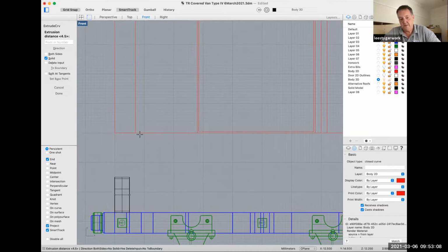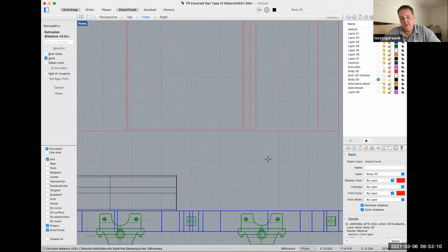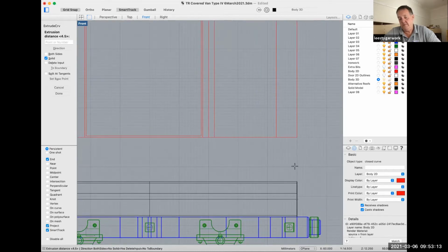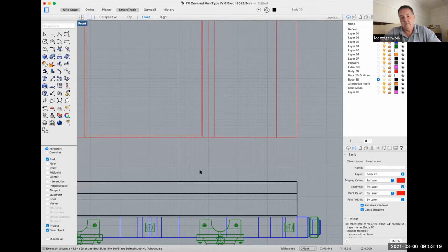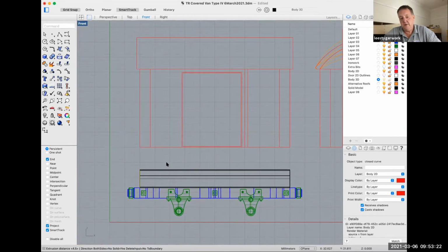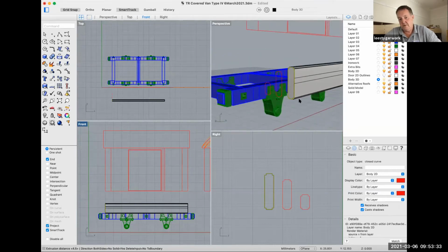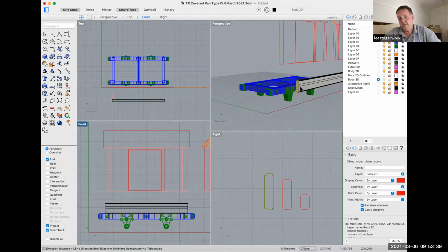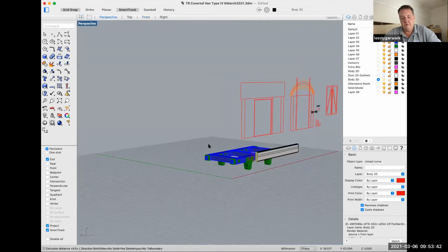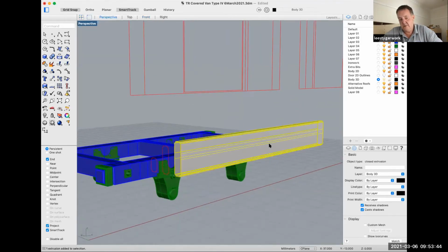This is where we start our plank in line with the body. We bring it over to here. We've got a snap on the grid size. We do that and just bring it back to full. In the 2D view that you're looking at the moment, we've got a black entity that looks a little bit like a plank. If we go to full view, you can see where the highlighted extrusion is still there, but what you've now got is the first of our 3D parts, which is a 3D plank.